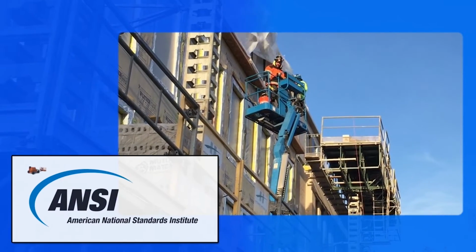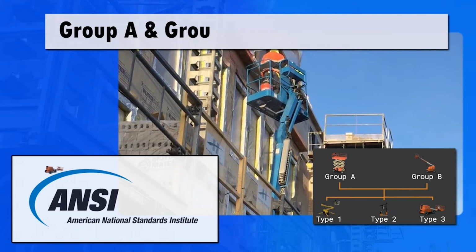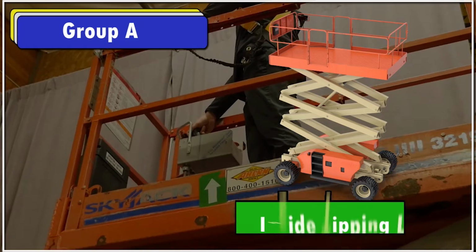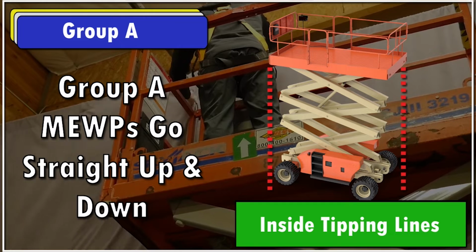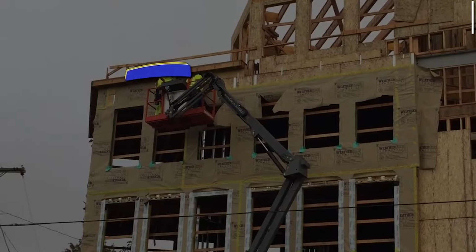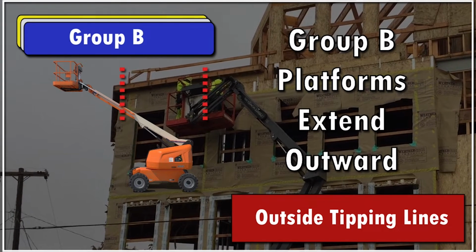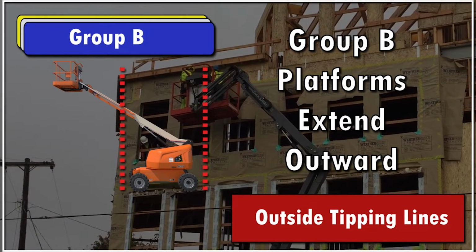The American National Standards Institute classifies aerial lifts, or mobile elevated work platforms, into two groups. Group A consists of mobile work platforms that move vertically, but stay within the tipping lines of the machine. Scissor lifts are an example of Group A mobile work platforms. Group B consists of aerial lifts where the platform extends past the machine's chassis. A standard boom lift is an example of a Group B mobile elevated work platform.